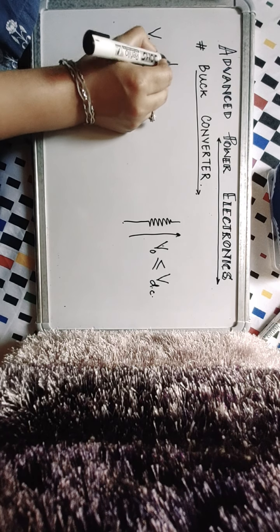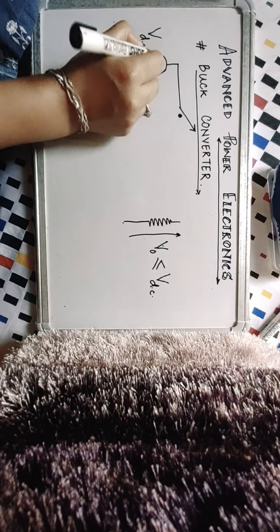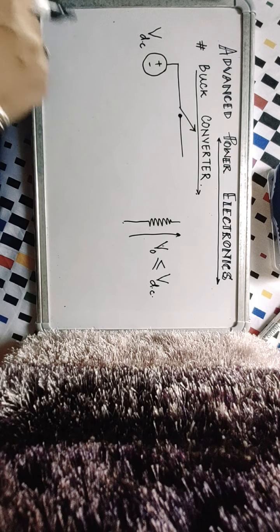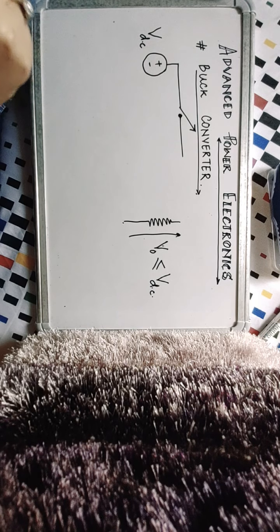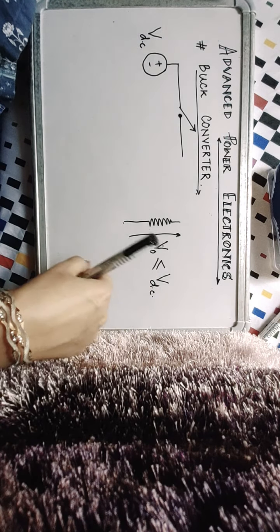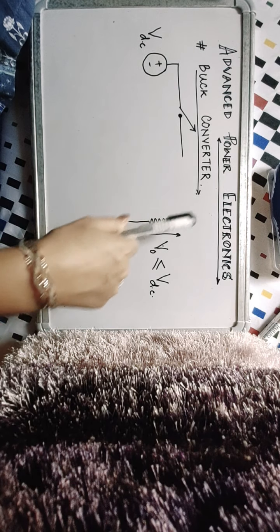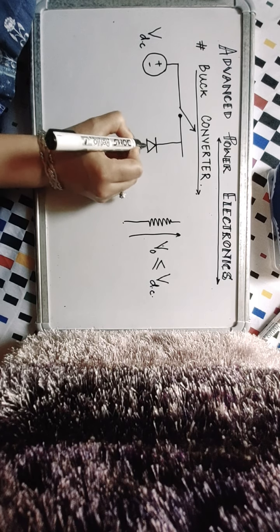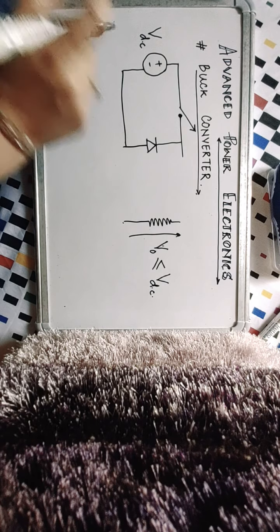To bring about this conversion, you use a fully controlled device. So you are essentially sampling the input and the output through this power electronics device. And as I have already explained in the previous lecture in the last semester, I have shared those links with you, in order to take care of the inductive energy of the load or the filter that you use in this circuit, you also need a freewheeling path, which is provided by a freewheeling diode over here, which is a fast recovery diode.